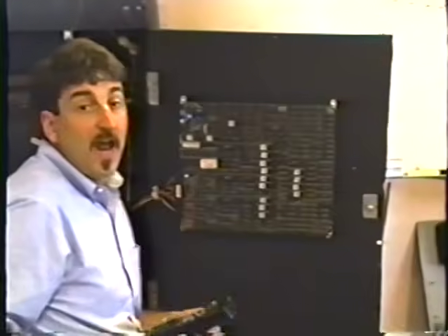When you go to put this guy in, you've got to be very, very careful that you don't bend a pin. If you've never done this before, if you've never pulled a chip out before, I'm not going to even try to do it with one hand. I'm going to put this aside for just a sec. If you've never done this before, don't even try this on a board you ever expect to work ever again in your life. Try this on a junk board.